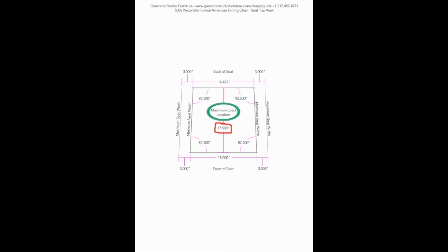Shorter, and the seat will not support the underside of the user's leg, causing numbness and fatigue. The width of the seat must fall between the minimum and maximum seat width lines drafted in gray. The angles defined by the design guide are fairly standard in the industry. However, they may be modified to suit a particular design if needed.